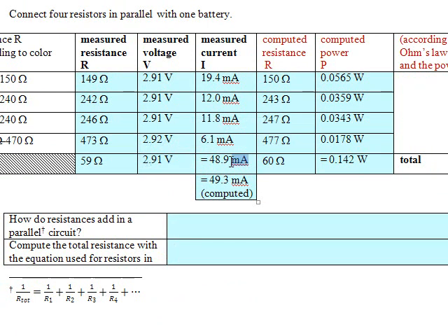And in any case, the total current is relatively high when you put them in parallel, which also means that when you have appliances in parallel, such as in your house, it increases the current, and therefore you need circuit breakers, because at some point the total current could potentially exceed the current for which the wires are rated, and all of a sudden you have an electrical fire.